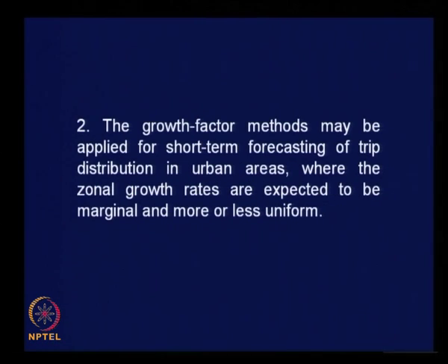The growth factor methods may be applied for short term forecasting. This is another situation where growth factor methods can be advantageously made use of. For short term forecasting of trip distribution in urban areas where the zonal growth rates are expected to be marginal and more or less uniform, right. In that case there is no problem and you can go in for application of growth factor method.